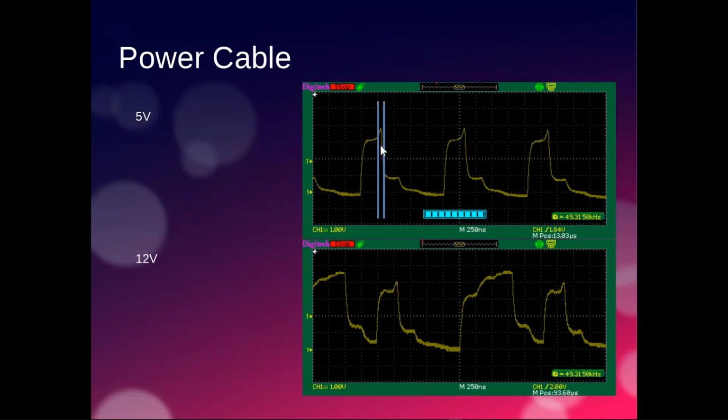That's not actually going to be a problem, because if you remember from our 2811 signal, when it sees the rising edge, it's just going to wait a period of time and it's going to sample it, and it's still going to be low at that point. So it's still going to read it as a 0, but it's awfully close to not reading it at all.